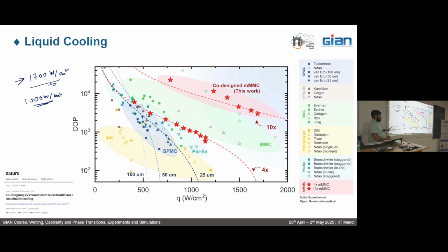Right now, especially in power electronics where they use semiconductor or GaN based devices, the aluminum nitride based devices, because of the very high heat flux, they are going towards the buried channels. And the fluidic system and the electronics are all developed over the same silicon substrate. So this is what the future has for this field, right?